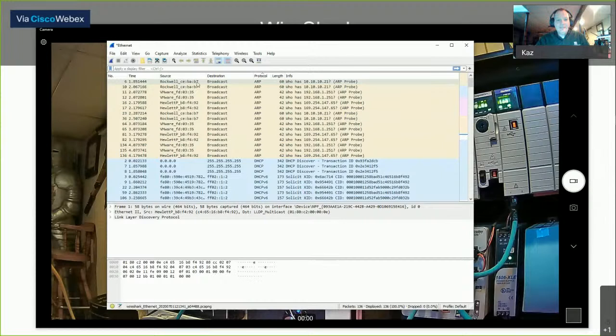And this CEBAB7 matches the last 3 octets of the MAC ID. The first 3 octets are the identifier for Rockwell. And it's telling me, hey, who has 10.10.10.21? That's itself. That is the IP address of itself. Remember, my VMware had 192.168.1.251. And if you want, you can pause and rewind and go back and make sure I'm not lying to you. But this 10.10.10.21 is the L36 ERM that we saw when I plugged it in.